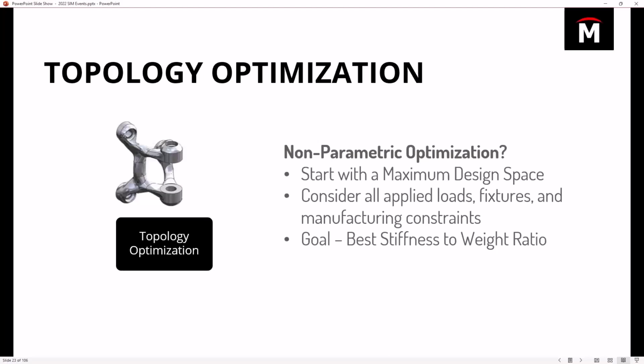It's kind of bulked up. And then I'm going to give it the same type of simulation setup, a few differences. And I'm going to ask SOLIDWORKS to figure out where it can remove material. What it'll do is iteratively pull little parts out of the mesh and run the simulation and figure out, oh, did this get better or worse? And then try different areas. So this is going to run quite a bit longer than the last studies. If the last ones took 20 seconds, this one's going to take 20 minutes. So keep that in mind.